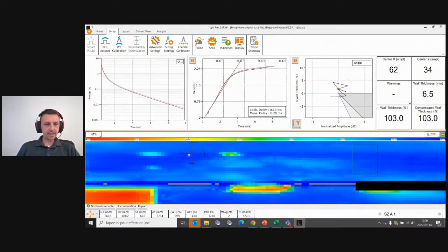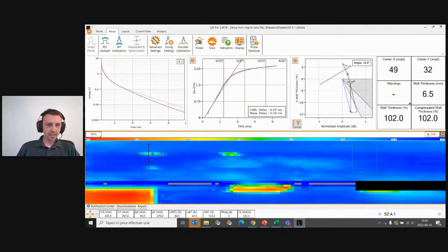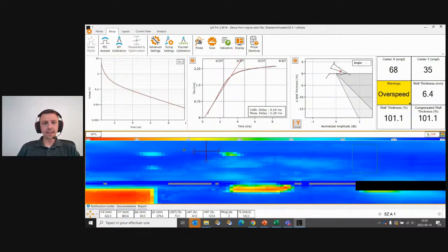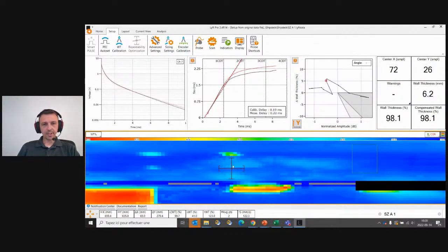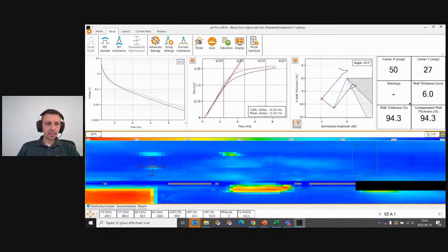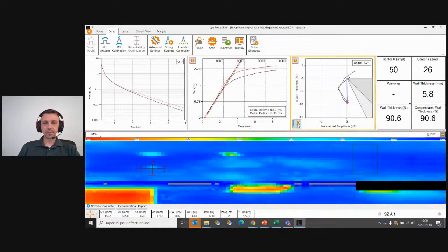So now let's see the defects. We expect to see 4 smaller defects, but unfortunately we see only 3. The fourth one is located right in the false positive indication, so we cannot see it or assess the indication. The first small one, if we use the Perm tool, you can see that this is clearly a defect there.